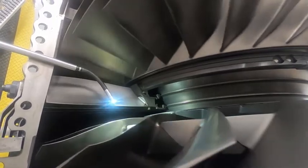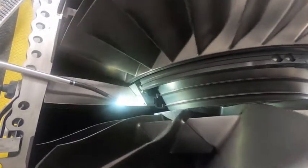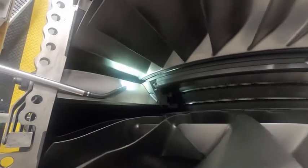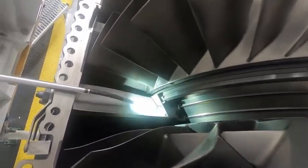After you get a good look at both the trailing edge and the leading edge, then you will move to the next port, which would be the 4:30 o'clock position, getting a look at the trailing edge of the second stage fan blades and the leading edge of the third stage fan blades.